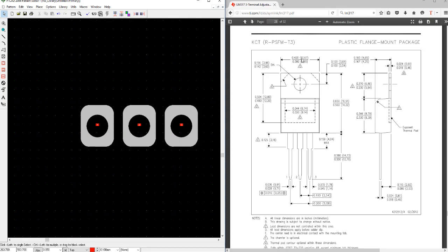4.65. Now just a note on this 10.67, that's a really odd value to work with. I typically work on a 0.05 millimeter grid, so I wouldn't go anything smaller than that. So I'm going to just round this down to 10.65 to facilitate my drawing of my block.